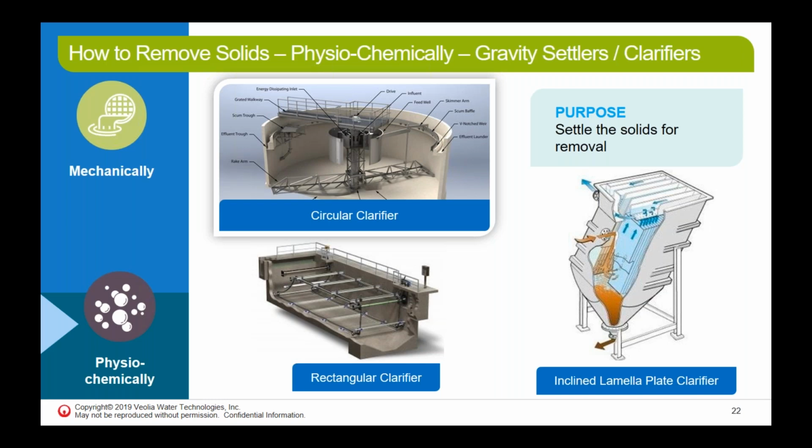So in those cases, we usually apply chemical pretreatment, such as cationic and anionic polymers or coagulants, or a combination of coagulants and flocculants. And those lighter solids start to agglomerate into larger particles. And once they form larger particles, we can apply similar principles as we were applying to grit removal, which are gravity precipitation, except in slightly larger vessels.